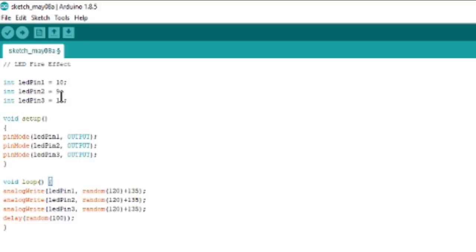Now, when you have this set up the way that you want it, then you need to, of course, plug in your Arduino to a port that's connected here. You can use this check mark here to verify. In other words, it'll do a test run of this sketch and make sure that all the lines communicate with one another. And then when you've done that, this arrow right here, you'll see it says over here to the right, upload. When you click that, it's going to upload this sketch exactly as you have it onto your Arduino and it will immediately start running it.